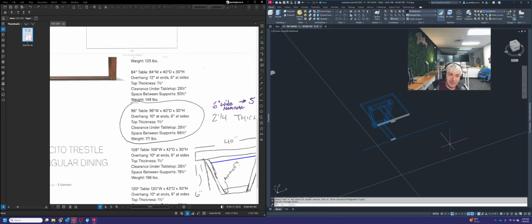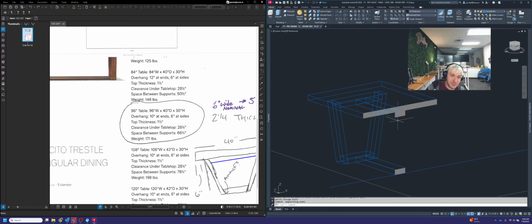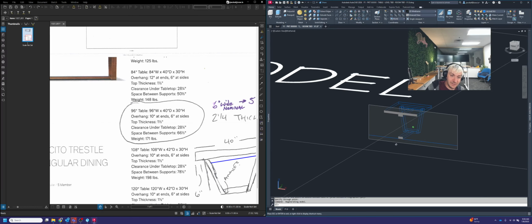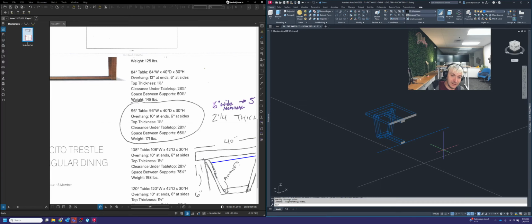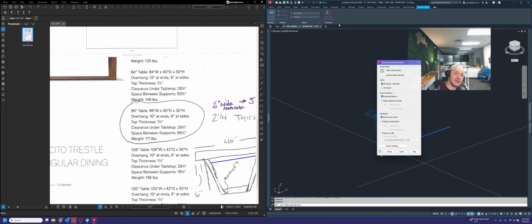So you can see exactly what it did. The gray boxes are where things are being chopped. The blue lines that you're still seeing there are things that are in the background. So now to make an actual section view off of this, you need to highlight that plane. And then this menu will change, and you're going to go down to Generate Section Block. And you're going to hit Generate Section Block below that drop down right there.